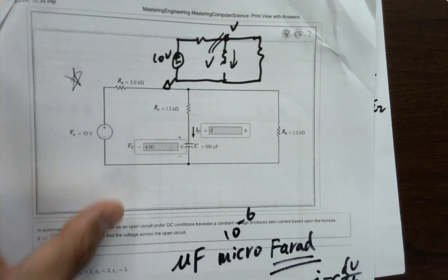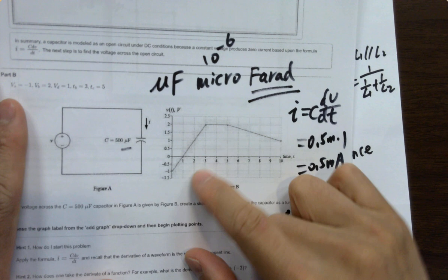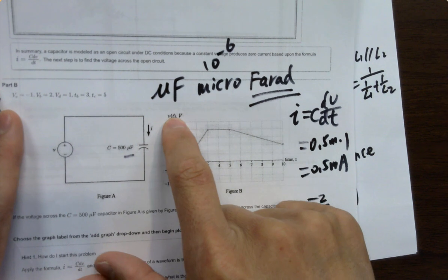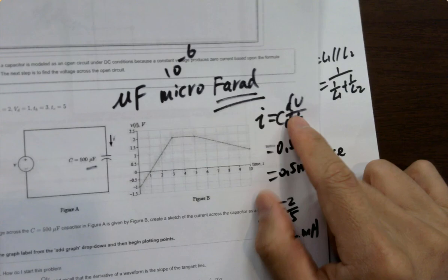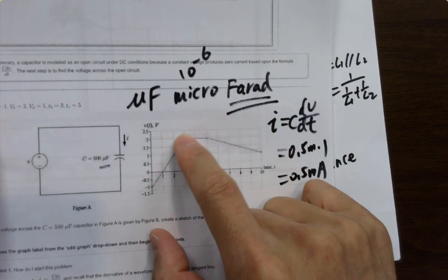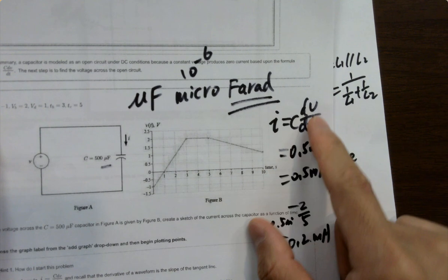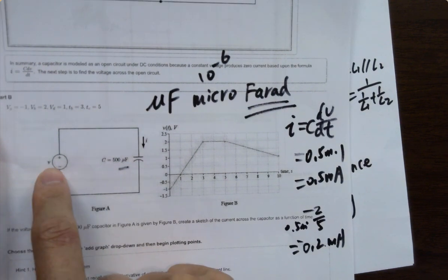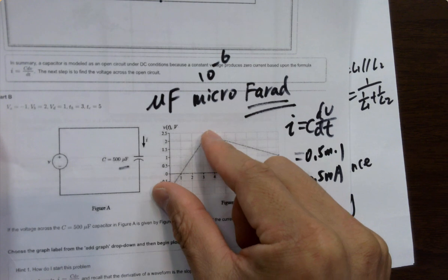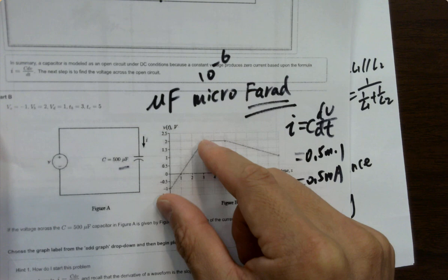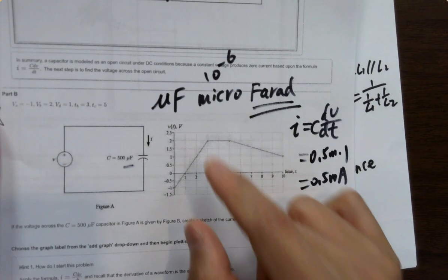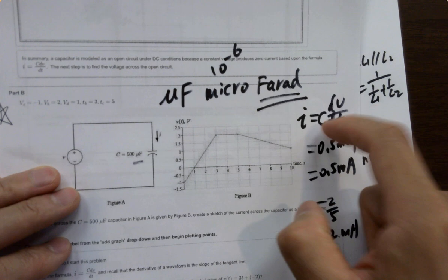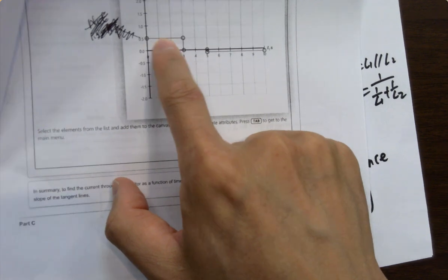And so you'll see the signals. The signal being given is like a ramp. All right, so that's V, right? Because we know the equation is I = C dV/dt. So the V is changing over time. That's why the slope here times C will be I. Here's the V, the source, doing the ramp voltage. And since it's linear, we just use delta Y divided by delta X, which is a constant. So the current times the constant is still a constant. So the current during this period, you just use this equation, and eventually you are getting a constant here for I.